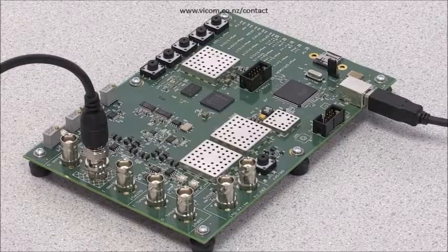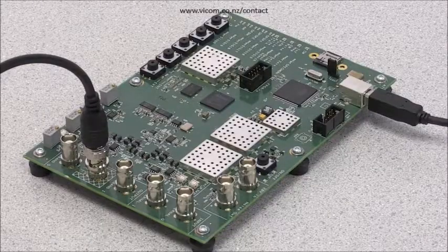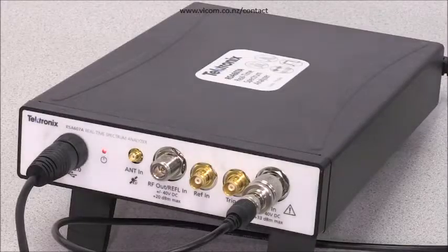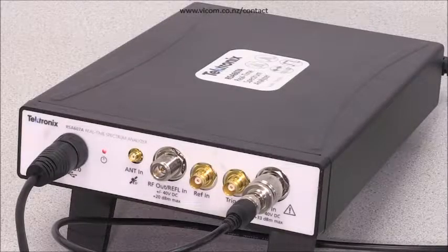And I'd like to show you a quick how-to video for doing Bluetooth pre-compliance checks on a Bluetooth device. In this case, I've got a demo board here available, and I'm going to do the test with this RSA 607A real-time spectrum analyzer. It's a USB analyzer that's connected to my PC. The PC will be running SignalVu-PC software to control the analyzer.